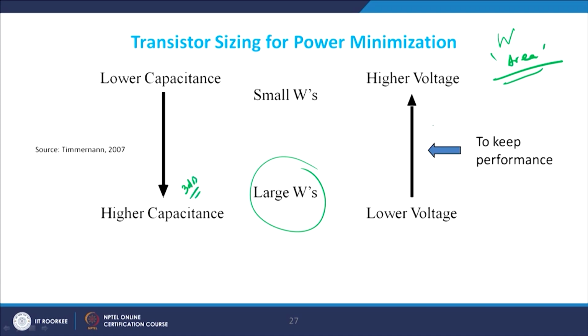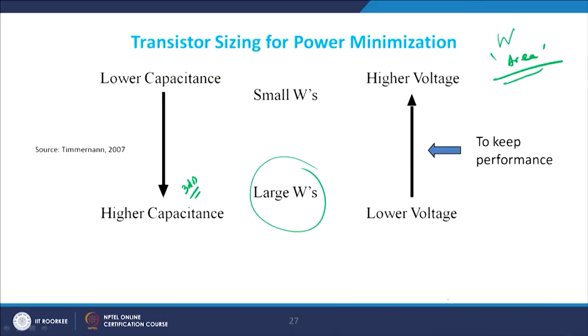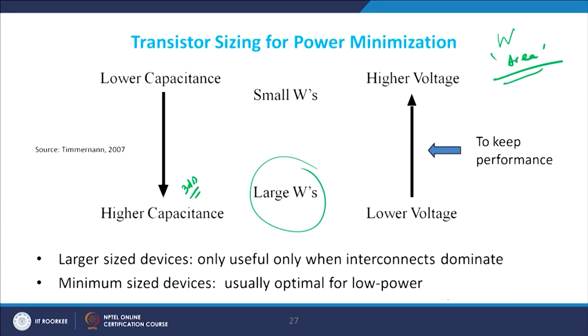What happens if you want to work at higher voltages? The reason is that sometimes my requirement is high performance, which means that I can't sacrifice on the performance, and therefore I increase the value of VDD. Once I make it larger, the performance increases, at the same instant of time the power dissipation also becomes large. So, this is a methodology which people use, what is known as adaptive scaling, in terms of both VDD and other devices as well.